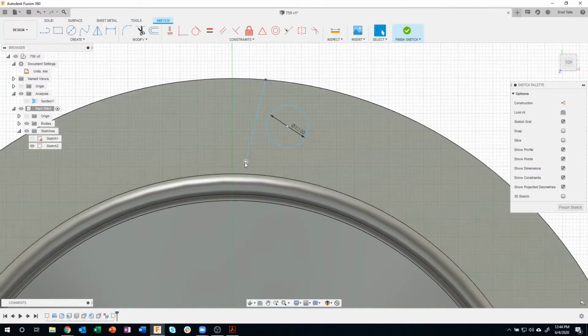It looks similar to that icon there, in a different orientation, but you get the idea. So I'm going to do the same thing here. I'm just going to click and drag to that point. I could do the same thing here, click and drag to that point there. You'll see that it snaps right to it. And if I were to move that point, that circle has to stay coincident with that point.